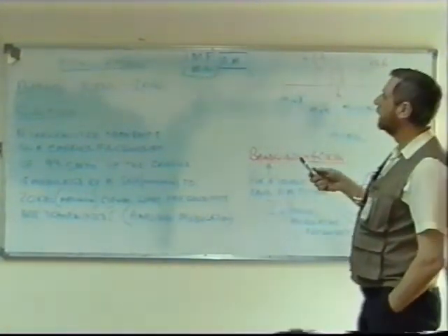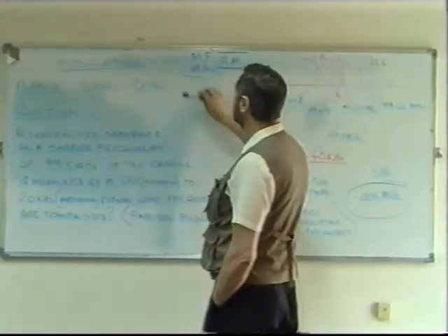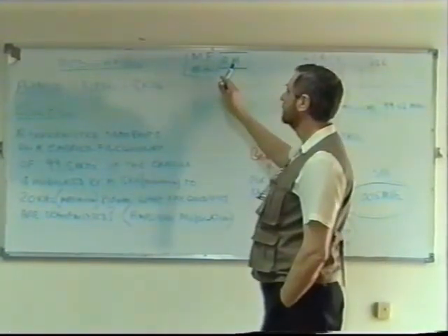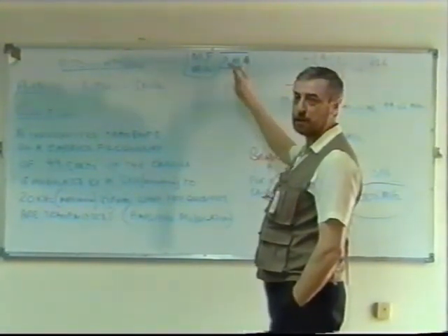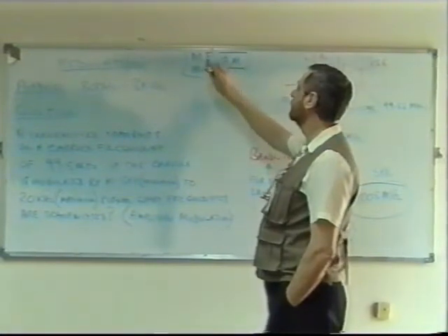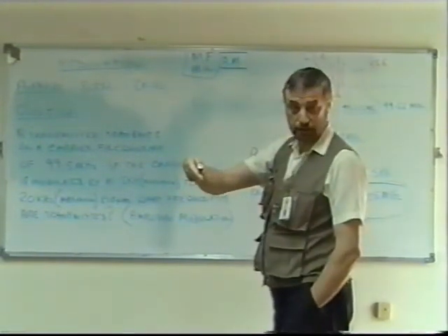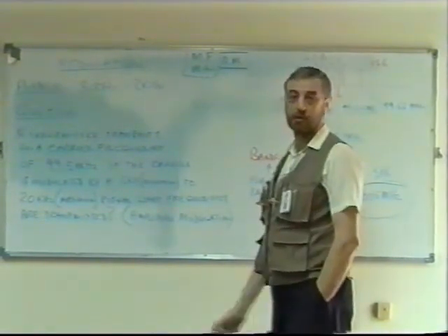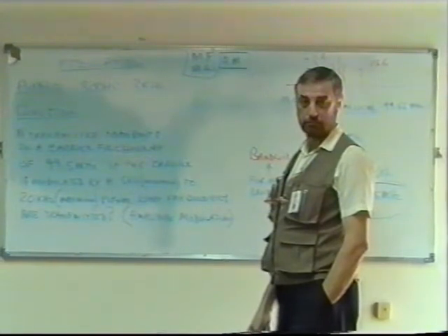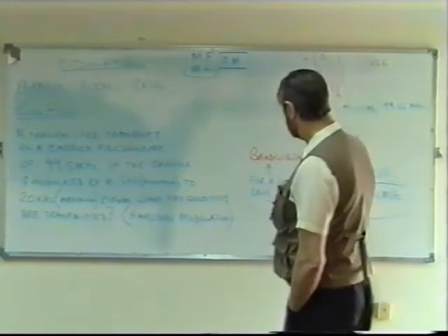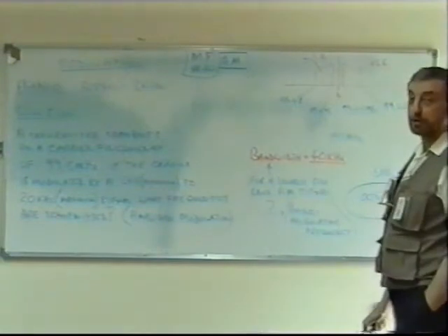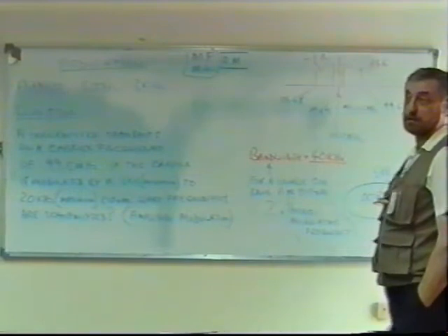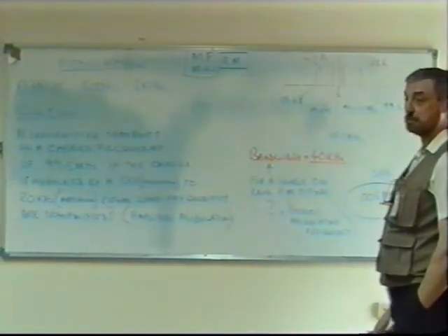But on your radios, particularly your car radios, if you've got a medium frequency band, sometimes they'll have AM written on it as well. Meaning that when you're receiving signals in the broadcast band, because it's designed for broadcast transmission, the type of modulation will be amplitude modulation. Sometimes it's called double sideband amplitude modulation because we're transmitting both the upper and lower sidebands. And this is what happens when you amplitude modulate your signal.